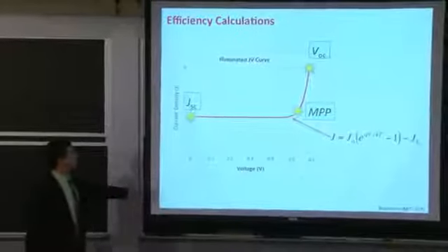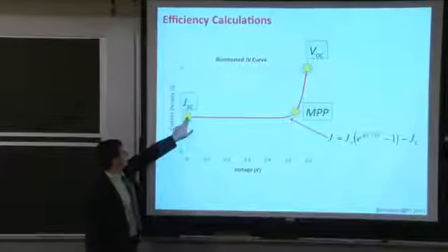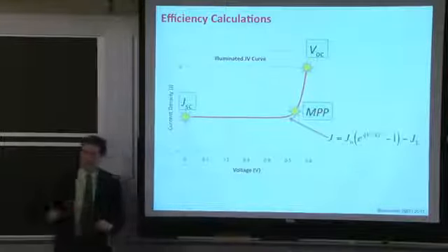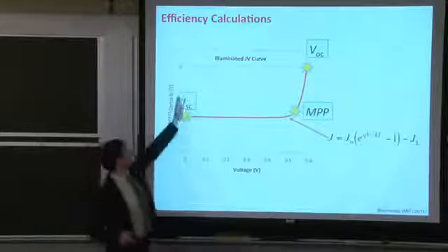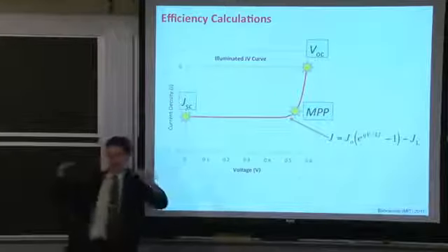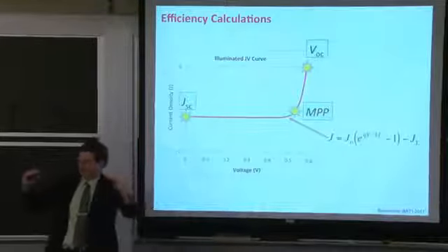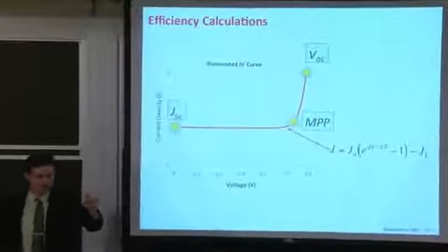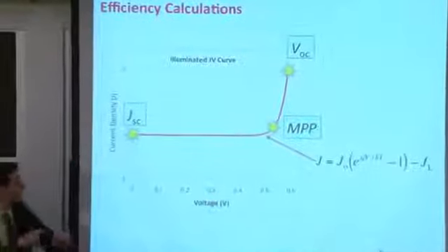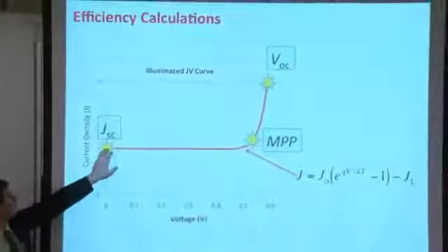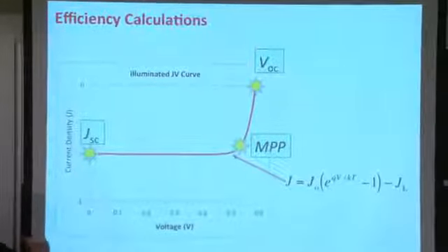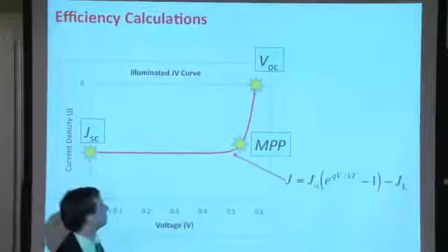We have the y-intercept over here. At the y-intercept, there is maximum current flowing through the circuit, but no power, because voltage is equal to 0. So remember, the Fermi energy is the same on either side. The chemical potential is the same on either side of the device. So there's no energy gain of the electron traveling through that external circuit, but there's a maximum current and no power flowing through that external circuit because there's no potential to be dropped across the external resistor.